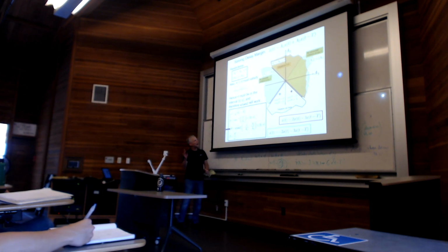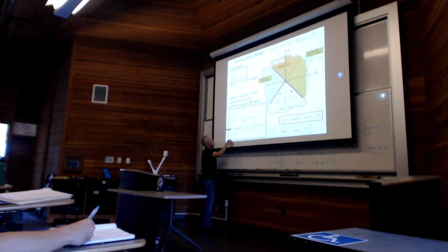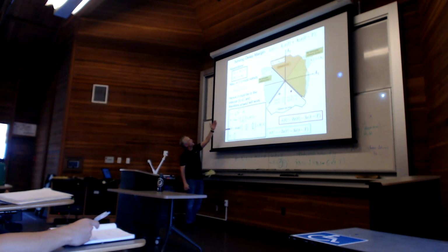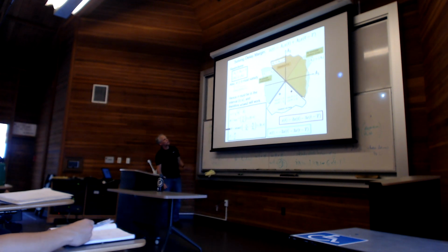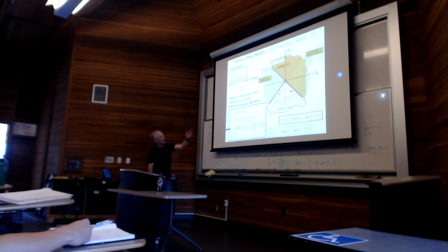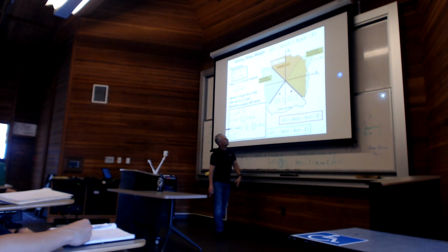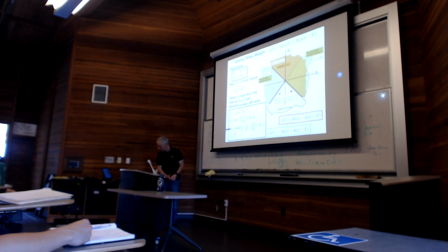So there's a 4-line MATLAB program that does this. You solve for omega, then you call atan2, and then you solve for t, and you do this only if A2 is bigger than or equal to A1. And so we can try these two cases out, and there'll be different solutions. There they are, the theta we're looking for, measured positive coming all the way around here. I'll let you work through those. Let me show you the code though.